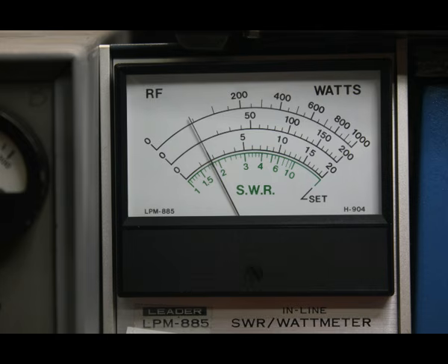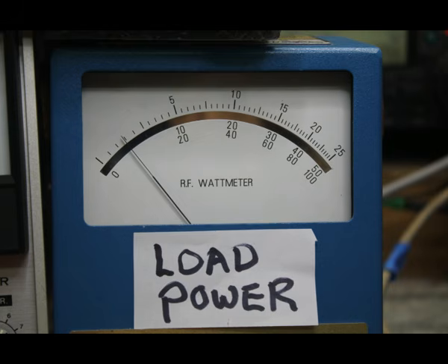So my poor little ICOM 746, because it's seeing a pretty high SWR now, has folded back and it's not delivering the 50 watts anymore, even though I didn't adjust the power setting. It's delivering 10 watts into the cable because it doesn't like the impedance it's seeing. It's not because there's reflected power going back into the finals. It just doesn't like that impedance that it sees when the coax is mismatched on the far end.